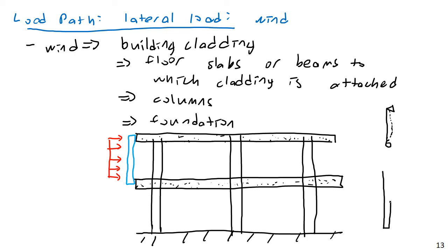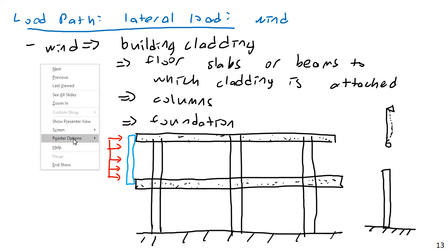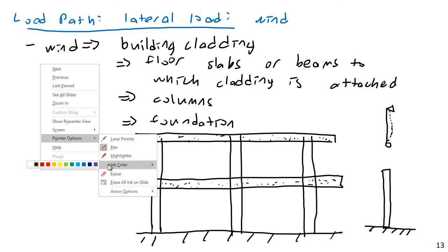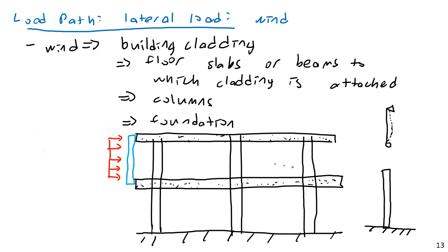and I'm treating this as an unbraced frame, like we don't have substantial bracing, so we'll talk about lateral load resisting systems later in the semester, but I just want to give a brief introduction here. You can also have a braced frame, where the columns are directly resisting lateral load and bending rather than something like an unbraced frame. But you'd have these loads here be the point loads coming in from the slab.